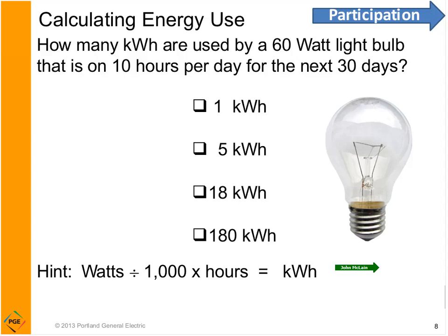How many kilowatt hours are used by this 60-watt light bulb if it is on 10 hours a day for the next 30 days? So this is a simple example of trying to calculate how much energy a particular piece of equipment is using in my monthly bill.